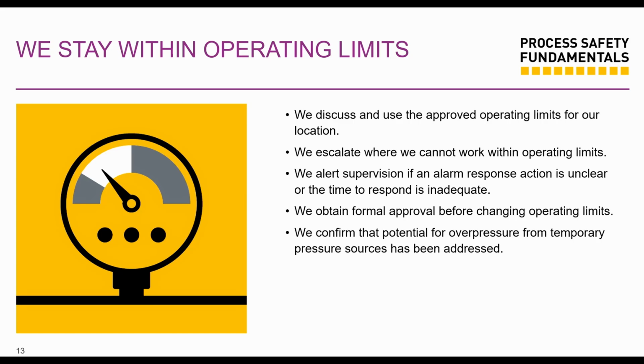There needs to be process safety time factored into the design, so that when the alarm goes, we still have about 10 to 15 minutes of operations to actually respond to it, or even 30 minutes. So we should design our systems with that in mind. Process safety time varies, depending on different companies and different facilities, based on what you're operating.